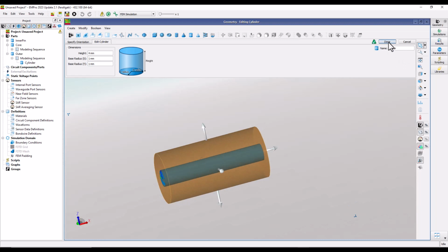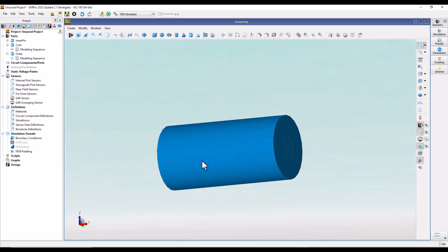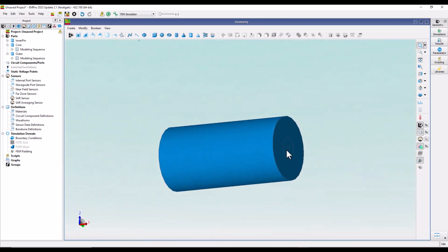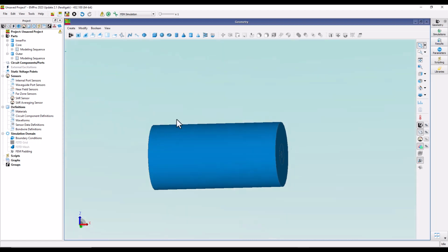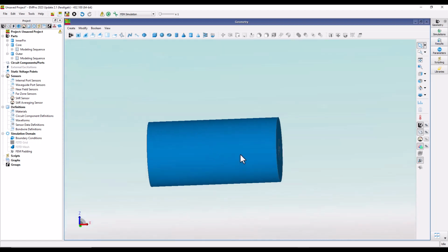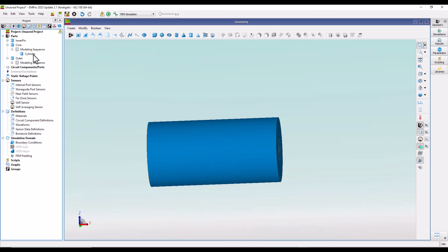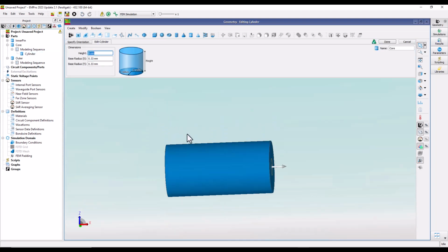All right, now one thing you notice here is all of these 3 are enclosed, but you needed the center pin to come out. That means the length of the core and the outer has to be a little smaller, right? And I'm making all these small things so that you can understand if you made a mistake, how can you go back and correct it, right? So the height of this core has to be slightly less. For example, here I would like to keep it 3.5. In a way, now it will give you like 0.5 mm of the center conductor lead.